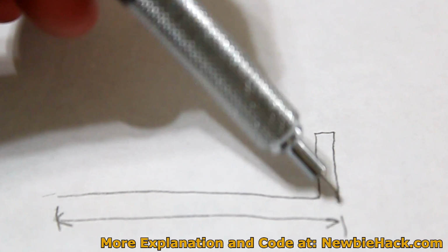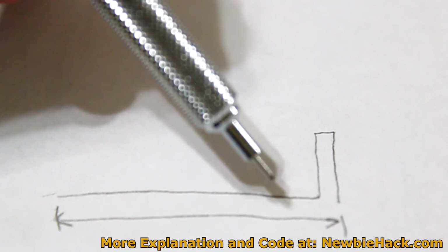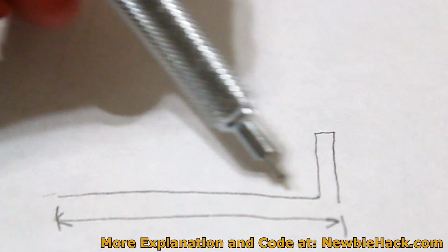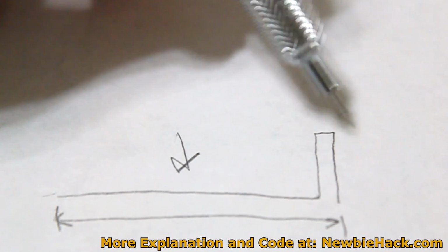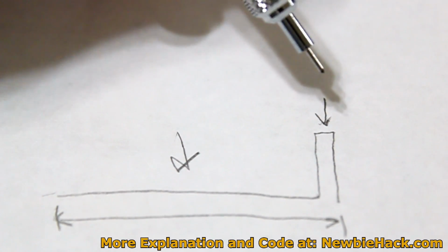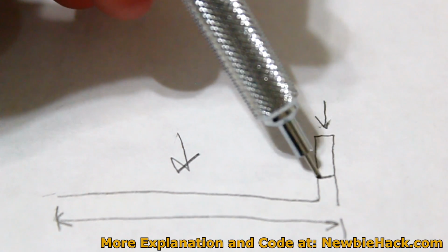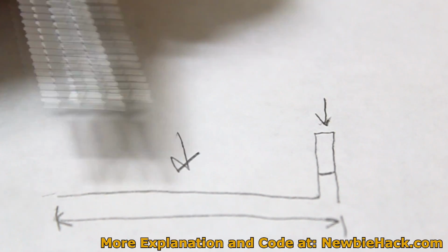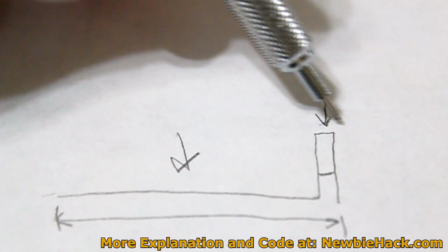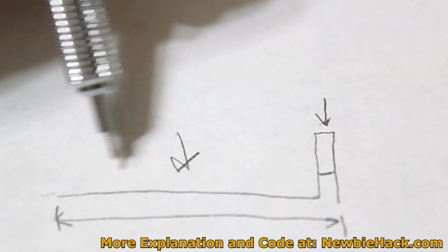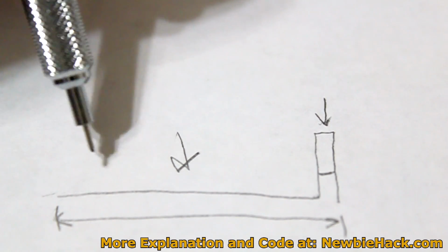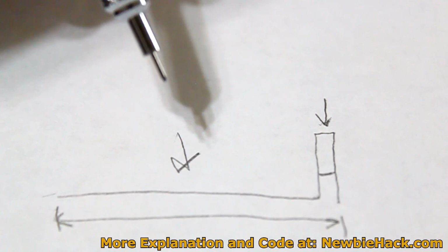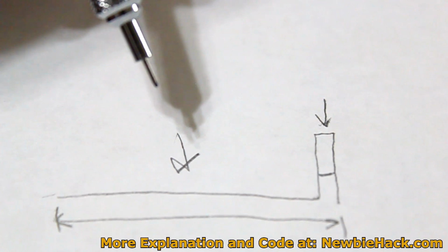And if we did it this way, we would have too much arithmetic in the program. We'd always have to subtract what we want here and produce what we want here. Subtract this part from this point, and then wait for that amount of time, and then do this. And we wouldn't be able to have any code in the middle of all of this waiting. So it's best to use interrupts, and we're going to be using timers for this.